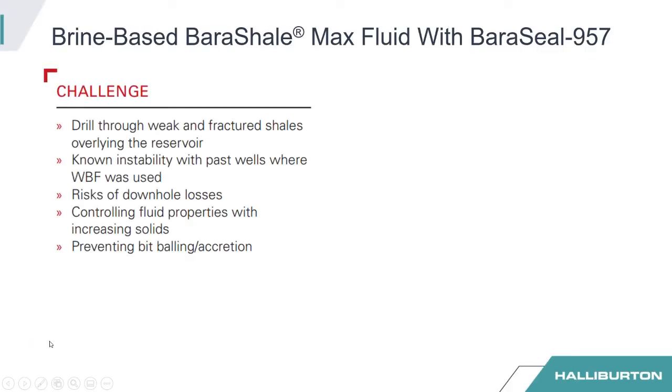Our main challenge was to replace oil-based fluid in an area where water-based fluids have had a lot of issues. We needed to drill through weak and fractured shales which were overlying the reservoir, and this was right at the curve section of the well. We had known instability in the past wells where water-based fluids were used, and they had failures to run casing. We also had to contend with the risks of downhole losses, the need to control our fluid properties with increasing solids, and the ongoing challenge of having bit balling and accretion occur.